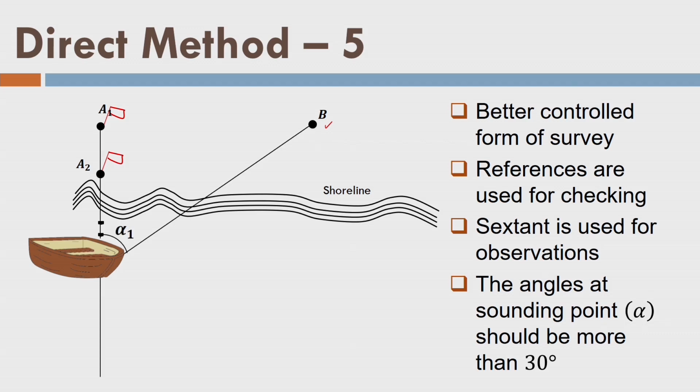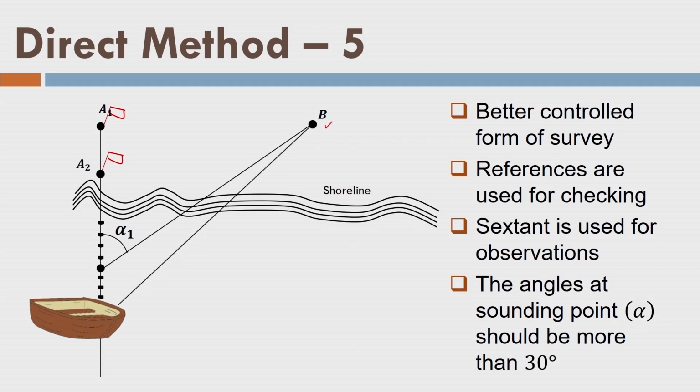So, this is the alpha 1 angle. I move to the next point now. In the boat again I have observed distances using the time ticks or the time interval, and again I will observe this angle alpha 2 here. We can see that we are measuring the alpha angles at a certain interval, maybe every 10th reading we are observing. What about the intermittent readings?